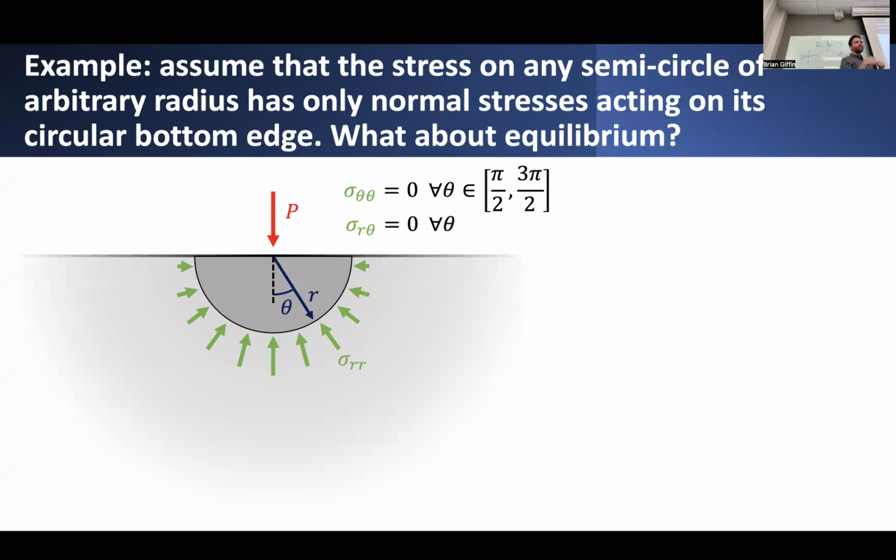The main rule of thumb that Saint Venant came up with is that if you have concentrated loads at the end of some long, slender member, and let's say that member had some characteristic depth h, then it usually is maybe 1 to 2 or so depth measures away from that kind of localized force. That's how far you would need to go before things smooth out. And it doesn't really matter whether you're representing it as a point load or not. But it fundamentally does depend on things like geometry.